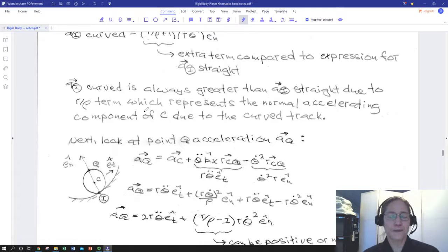Okay, so if we're looking at maybe constructing bearing surfaces for two rolling wheels, like a ball bearing in a race, the surface of that bearing race is going to have to exert a force to satisfy that normal acceleration. So we can expect for the same mass that we're accelerating around, we're going to expect higher forces necessary to get it to do that.